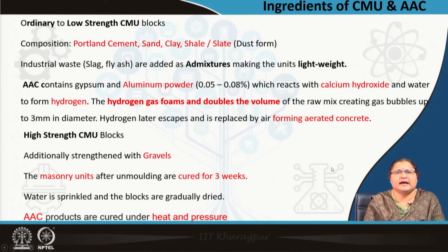Coming to the high strength CMU blocks, they will be added with further gravel, that is coarse aggregates, and they also require some curing for 3 to 4 weeks. Water is sprinkled on the blocks, whereas as I told you, AAC products are cured under heat and pressure.